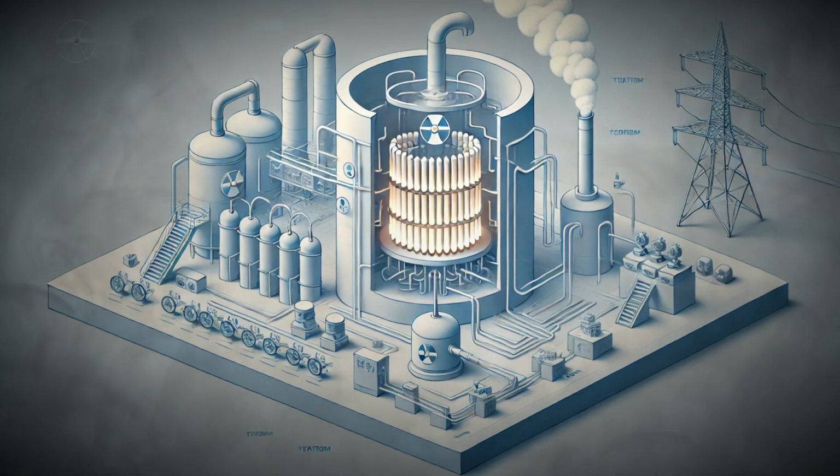In the steam generator, the primary coolant heats the secondary water, which turns into steam that drives the turbine. This design keeps the radioactive coolant isolated from the turbine and generator system, reducing contamination risks. In boiling water reactors, the system is slightly different because the coolant itself is allowed to boil directly in the reactor vessel, producing steam that goes straight to the turbine.